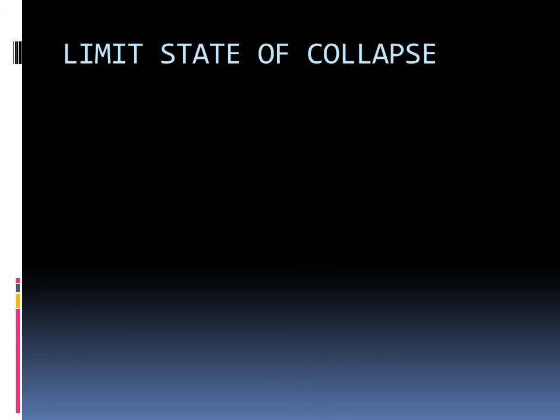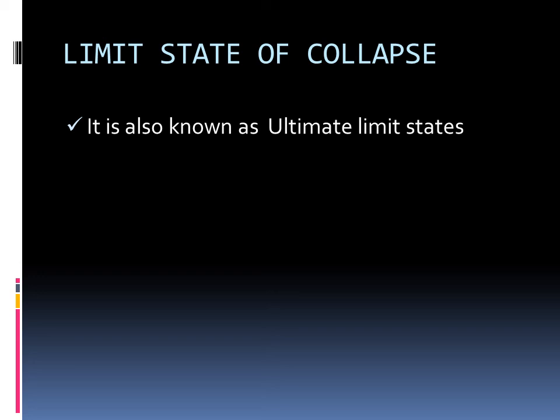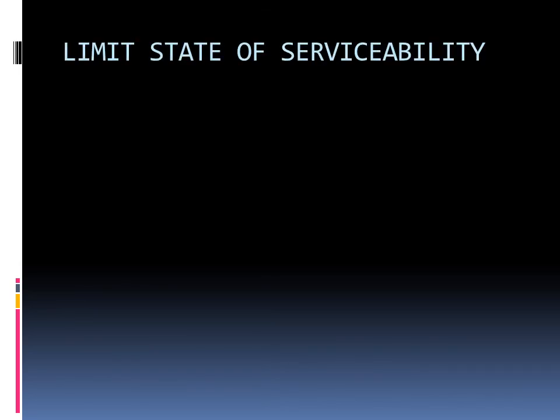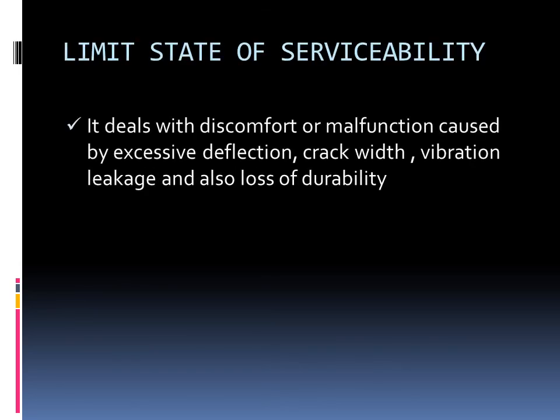Limit state of collapse. It is also known as ultimate limit state. It deals with strength, overturning, sliding, buckling, fatigue, fracture. Next is limit state of serviceability. It deals with discomfort or malfunction caused by excessive deflection, crack width, vibration, leakage, and also loss of durability.